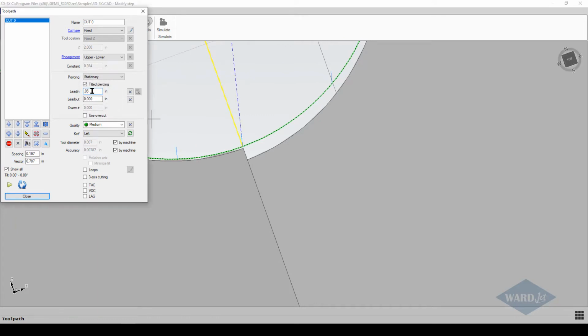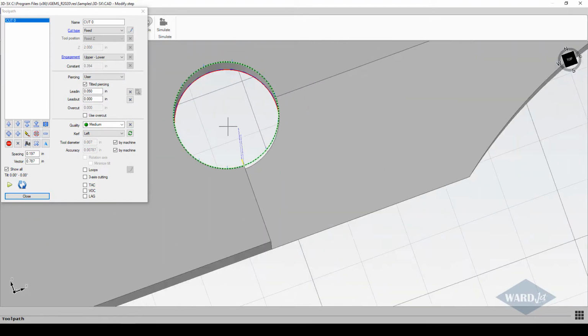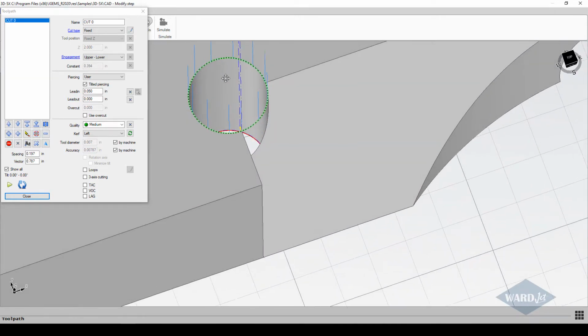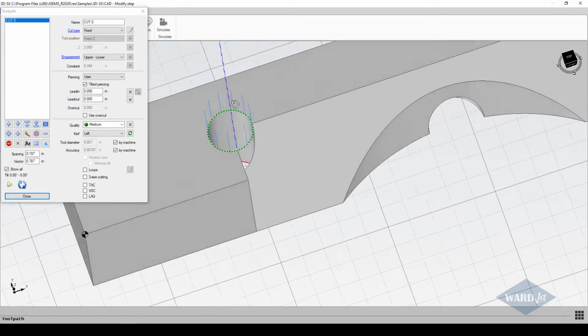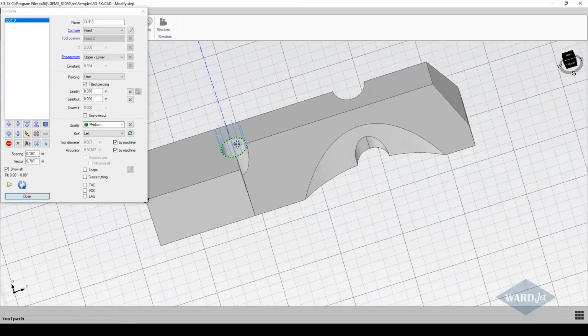and we'll just do a shorter lead in there. And then for water only cutting, you can set this lead to either blind, where it's actually not going to pierce here, it'll actually pierce on the edge of the material, or you can set it to user will pierce and come in there. So you can see this green line here that represents where the toolpath is actually being projected to.